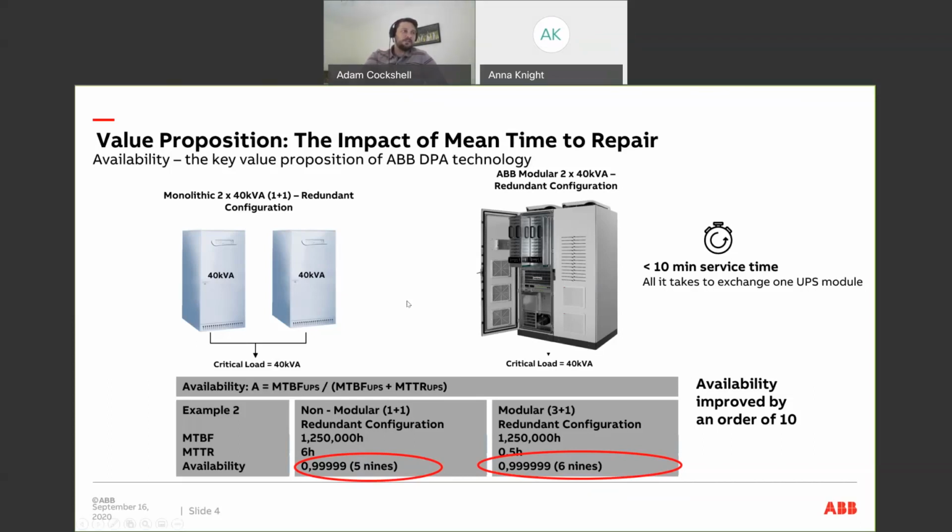What it also does is, if there is any unforeseen failure or problem with the UPS, it can remove a module automatically from the system, and you've still got your redundancy built into the UPS itself. And if the question is pertaining to the fully redundant system, the one with 2 frames, an active frame on this side with a passive frame in the middle and another active frame on the other side, you just increase that redundancy and availability.